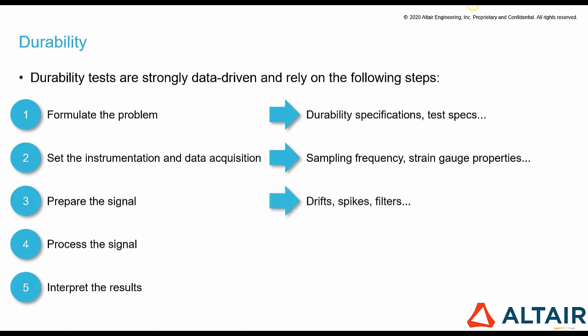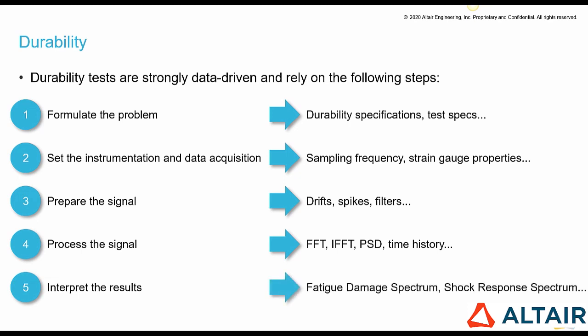Third, preparing the signal means that drifts and spikes should be removed in time domain analysis, whereas filters in the frequency domain may also be applied. The fourth step is that signal processing will navigate from time domain to frequency domain, compute power spectral density, and generate a time history based on a PSD, for instance. And finally, interpreting the results helps to calculate the damage and the maximum displacement that our component is exposed to.